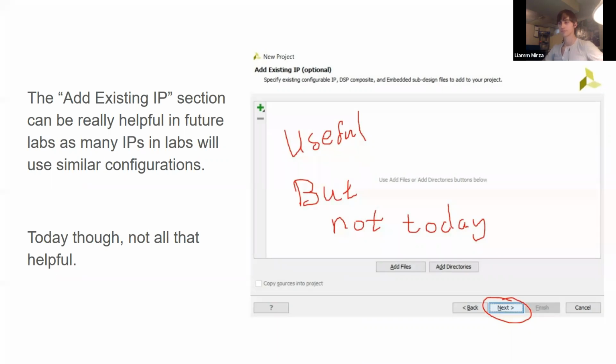Do you want to explain what this is used for? Yeah, so if you're doing MicroBlaze or anything like that, or maybe even put together your own designs, you could save it as an IP and import it whenever you want. It can make it a little bit easier to import large amounts of Verilog files without messing things up, but I didn't use it much in this course. You might not find a reason to use it, but it is pretty useful. And if you can learn how to use it, it can make your life pretty easy as well. Like if, for instance, you make the BCD decoder an IP, you just import it, and all the files come right in.